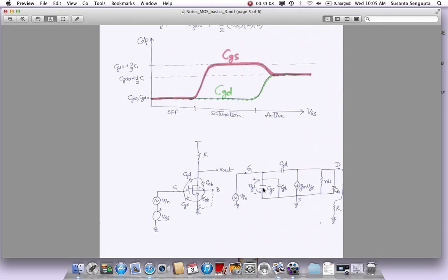I'm assuming here that you know some concepts of LC, but if you don't, please go refer to parallel LC resonant tank circuits, and how a lossy capacitor could be resonated out by an inductor in parallel to it. That way we extend the speed, because now that capacitor is not going to limit or give you a low pass type transfer function anymore. That capacitor has been knocked out by an inductor because it's resonating, and we use that technique in the RF world all the time to resonate out lossy capacitors with inductors, and extend the frequency of operation for the circuitry.